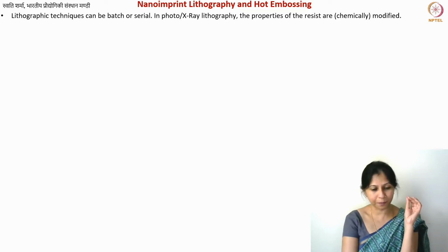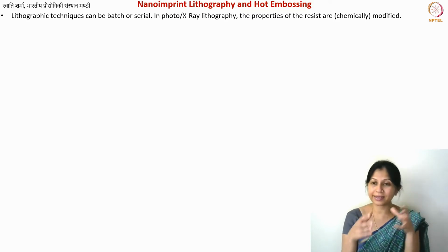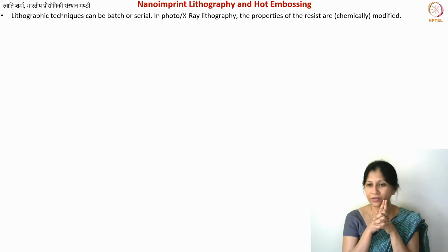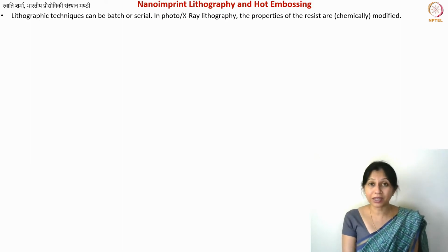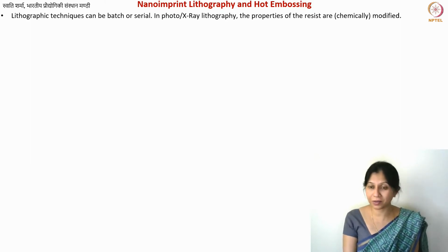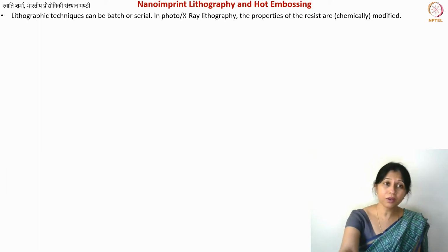After a certain point, your material densifies so much that you cannot really shrink it any further when the structures are extremely small. But still, if you make, let's say, a 10 nanometer structure and your carbon yield is 30%, then you can get a 3 nanometer structure out of it. If it is completely translated at that scale, you can get very small structures. But how do we perform lithography at nanoscale? There are various techniques. One of them is known as nano imprint lithography, and a variation of that is also known as hot embossing. Okay. So what are these techniques?